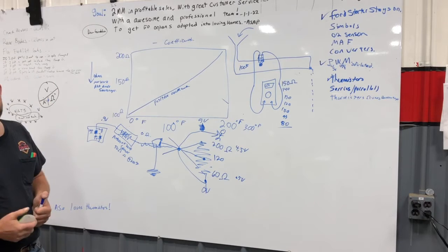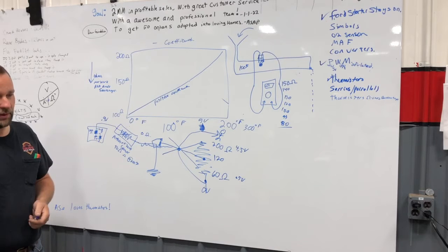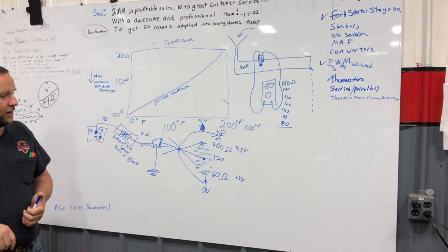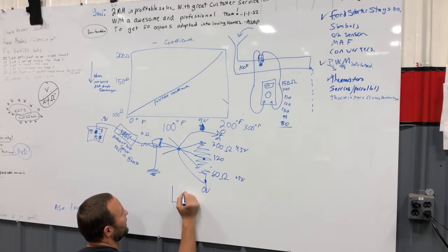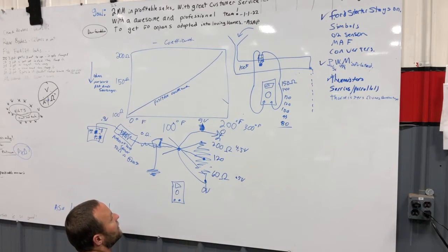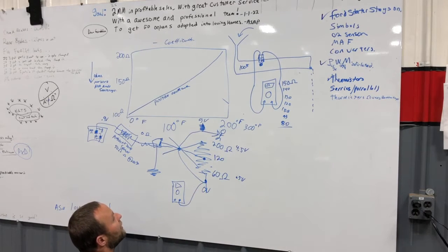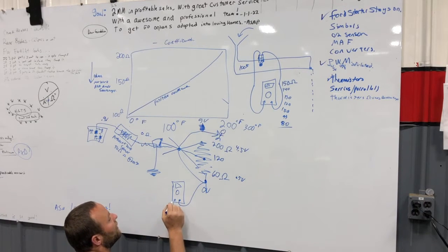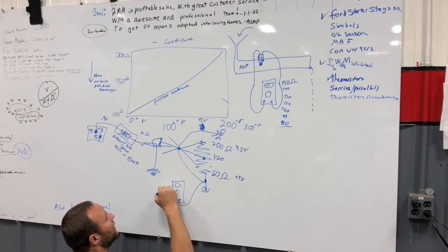Yeah. So how would you test it? Let's say that car's fuel gauge was completely on full, and you knew it was not full. How would you test it? Here's your ohmmeter, or voltmeter, whichever you'd like to use. You'd have to reach it in the gas tank, right? That's where it's located. So where would you test? Andrew, do you know? Probably the positive and the negative, right? Like the 0 volts and then the 5 volts, at the top. Yeah, you could do that. I would go to the plug, there's going to be a plug, I would go to here, basically.